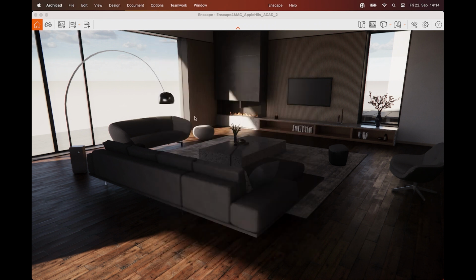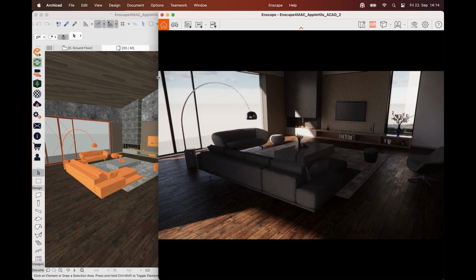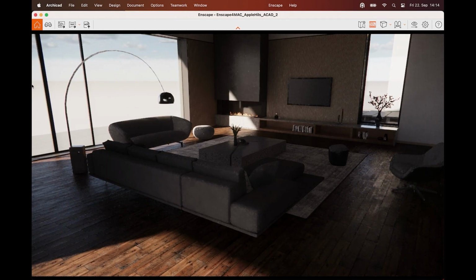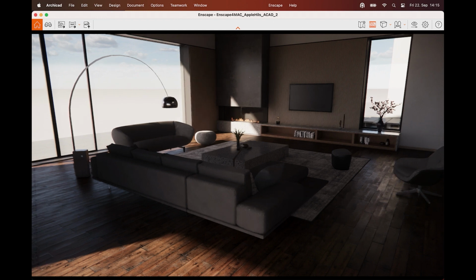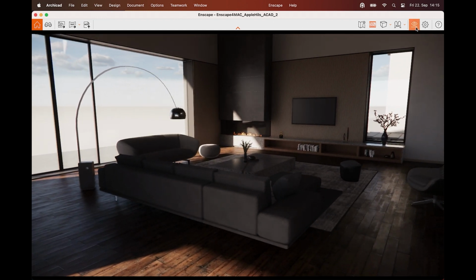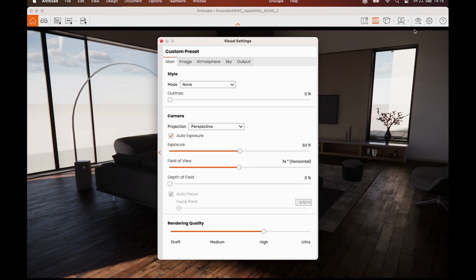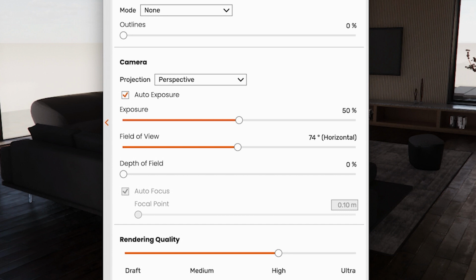We can enable the Save Frame option to see the extents of our image to be generated. Use this to set up the perspective you want to go with. Tip: if you are in a closed room and don't seem to have enough space to get just the right view for your export, change the field of view angle. You can find it back in the visual settings.